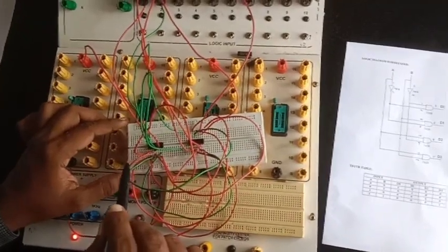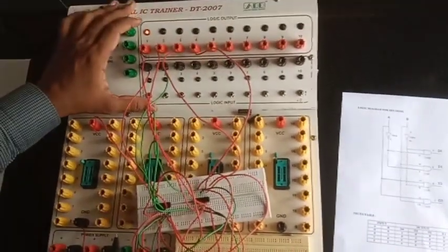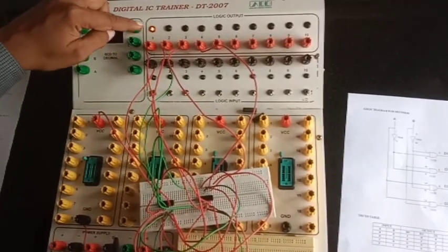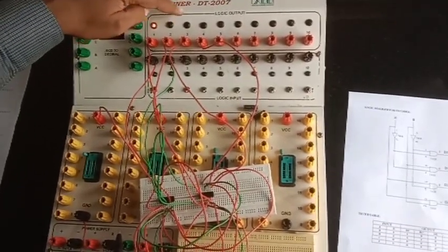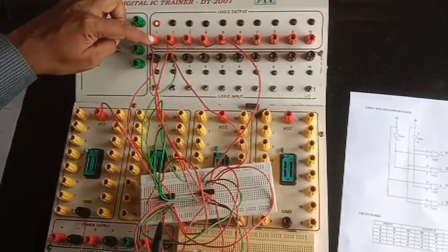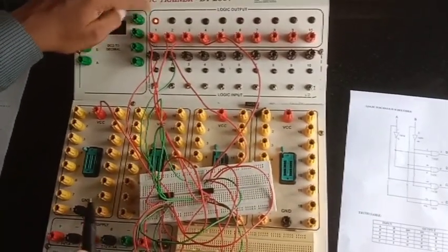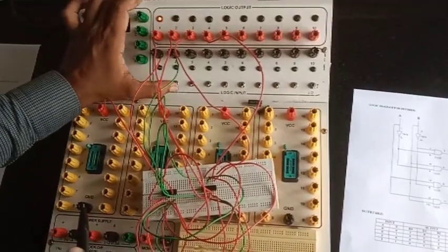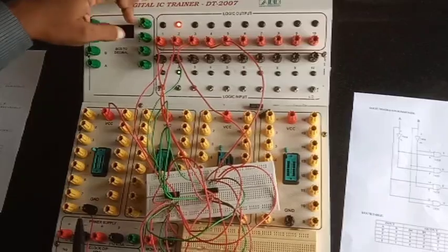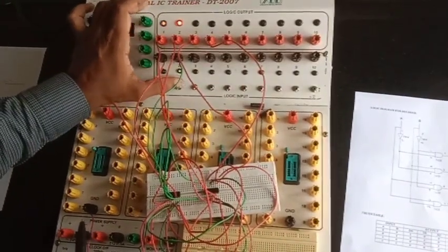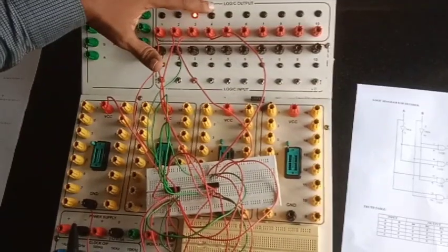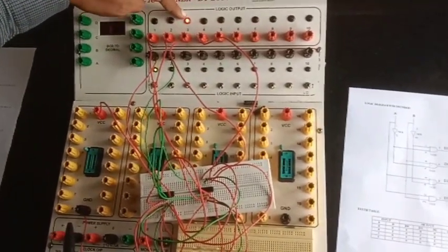All the connections are made as per the logic diagram. Now I am going to give the input. A is equal to 0, B is equal to 0 in this case. So I am getting the output in D0. This is D0, D1, D2, D3. Only D0 gives the output, so 0, 0 is decoded into 1, 0, 0, 0. Next case 0, 1 means I am getting the output in D1, remaining values are 0. Third case 1, 0 means I am getting the output 0, 0, 1, 0. Only D2 is high.